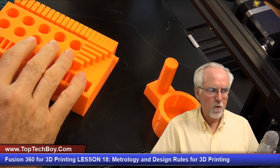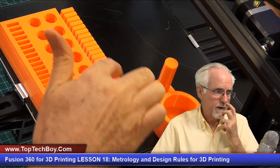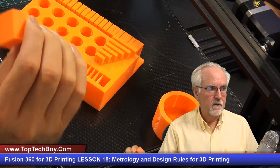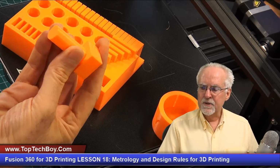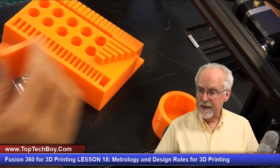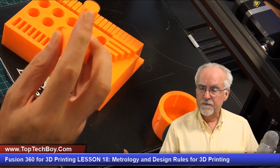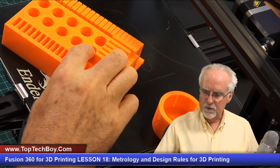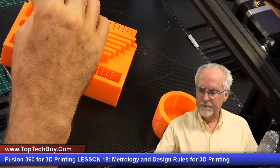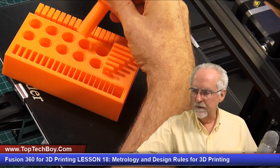Okay, now the corresponding things over here, I'm going to come back and do those last. Now what I'm going to do is look at my axle, my pin and hole connections. And remember, this one here was a 15 millimeter peg and this was a 15 millimeter hole. And so this one would be 15.1, 2, 3, 4, 5.